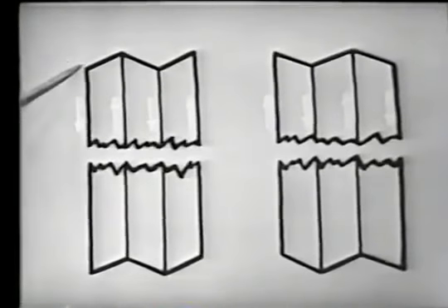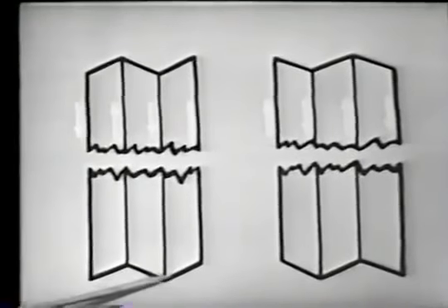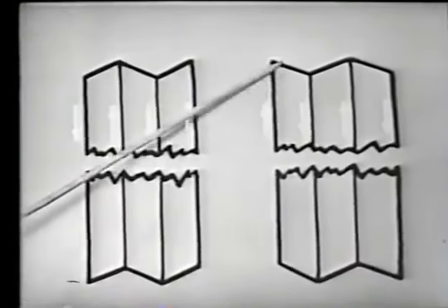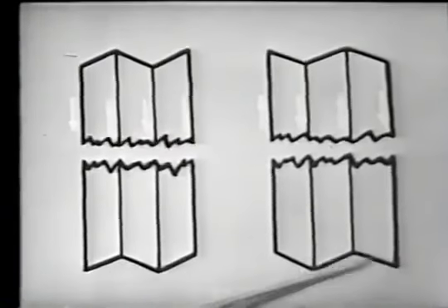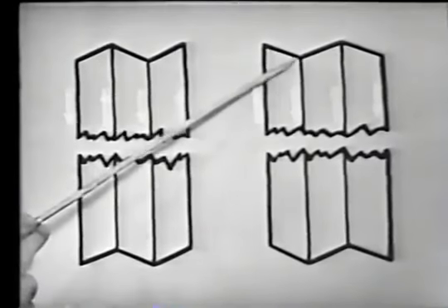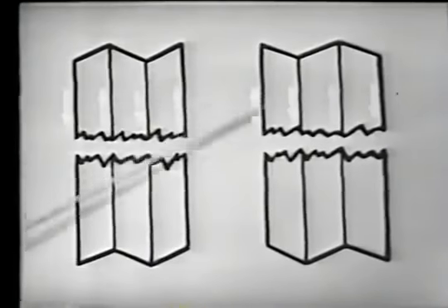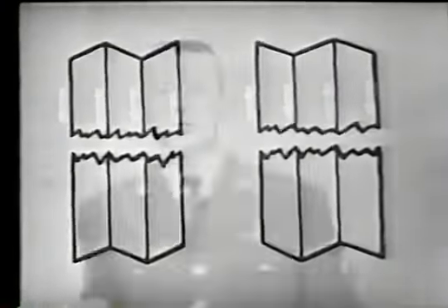Now this is representing the deformed layers to produce one alternation. Here, the deformed layers for the other alternation. And let's notice that the deformities are opposite for each alternation. Now, if the crystal is made to operate on the 5th overtone, it breaks down into 5 layers. If it's made to operate in the 7th, it breaks down into 7 layers and so on.